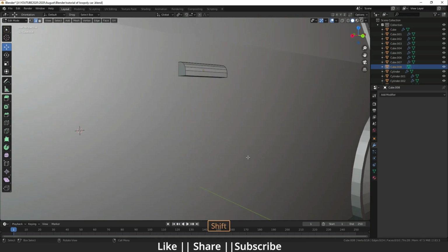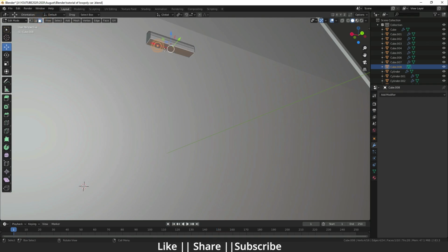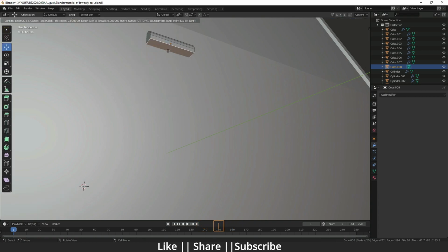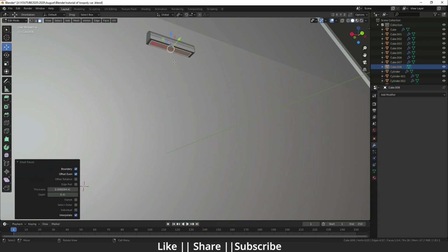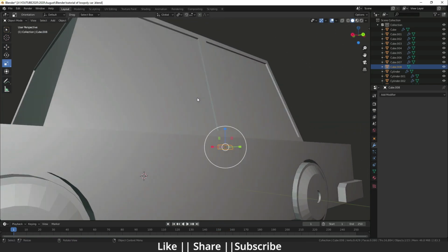Yeah, okay, and select that back face, do inset like that. But right now here you can see that inset is not working properly, so we do the same thing here: apply the scale, then do inset, so it's applied perfectly, and press E for extruding inside. So we have a handle here, you can see.